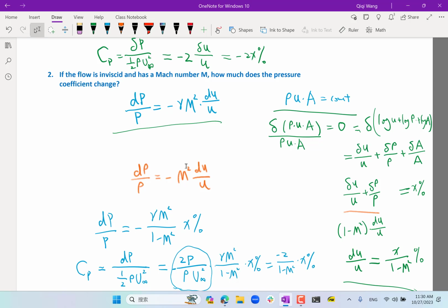And for low speed flow, what is usually the change of pressure? You can usually compute it from Bernoulli's. If you have air density of about 1, and a flow of even 10 meters per second, multiply 1 with 10 squared, that's 100. So what is 100 compared to 100,000? The ratio is so small that it is practically negligible. That's what we mean by incompressible flow.